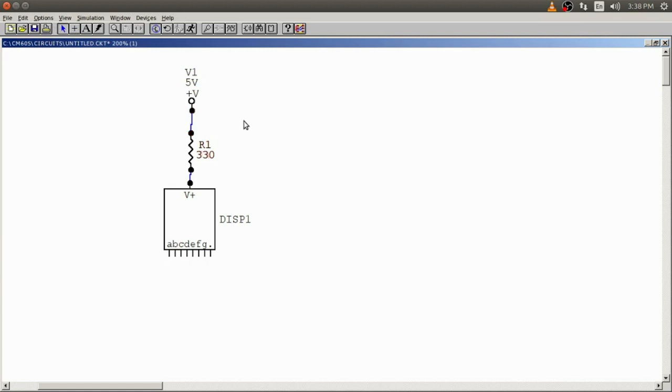Now this connection is made. Here, this display, now how it works, I have to connect the other end to the ground. You remember these diodes are common anode. So if I connect one end to the power supply, the other end, that is the cathode, I need to connect to the ground so that I can get a display lit.